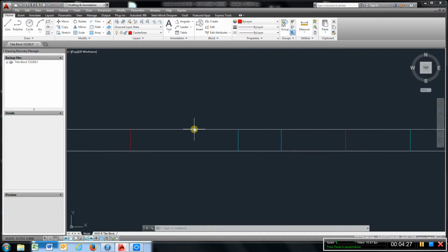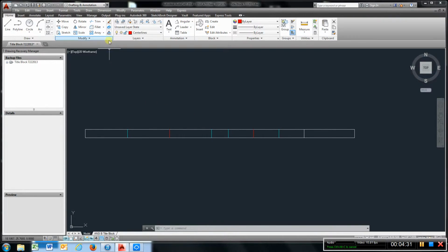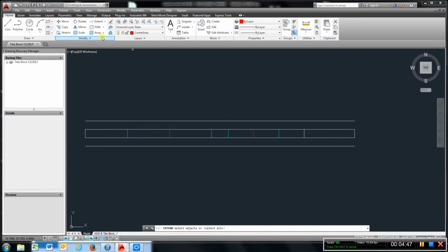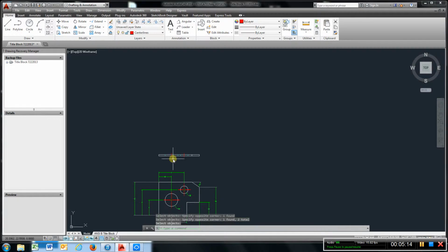line flush like that. So if this is 1/4 inch, I'm just going to temporarily offset another 1/4 inch. So I'll hit offset, enter, select that line, move up, select this line, move down, and then we can go to this drop down button next to trim, go to extend, and I'm going to choose where I want to go, right click, and choose what I want to go to up to that line. And we'll go back to extend, choose this line, right click, choose the center mark. Now you can go to erase and erase those temporary lines. Now we have our top view completed.